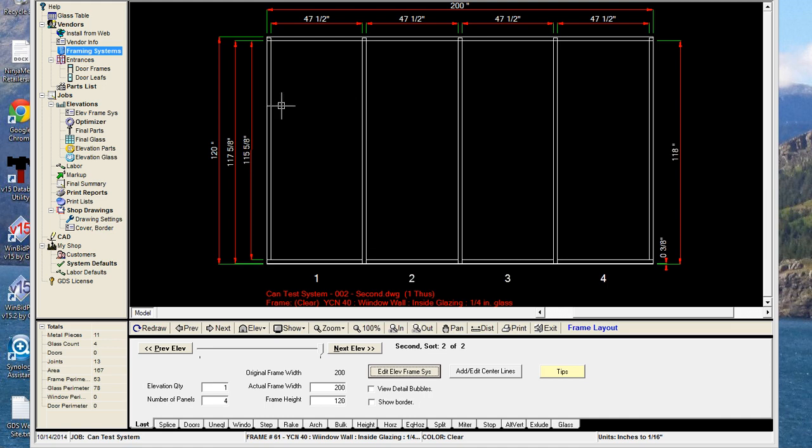Now this is for the jamb. The vertical material, the mullions, are a little different. They're extending through the sill material on top of the sill receptor, so that's only taking 3/8 of an inch off the bottom. And then at the top, it would have been taking 2 inches off, but I added the 1.5 inches. So let's do the math on that.